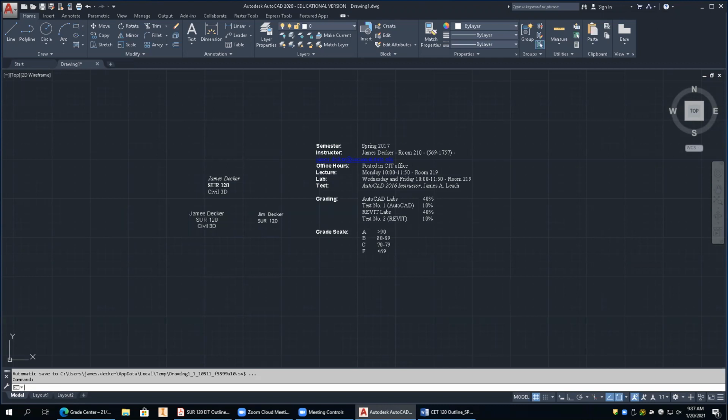The easiest way, draw a diagonal line from there to there. The midpoint of that line will be the geometric center of that box. So this is suggesting that you use a middle justification. If you snap a middle justification point to the midpoint of that line, it'll pop right in where it needs to be. Use a height of 0.25, type that in, and when you get done, you erase this line and nobody even knows it's there.